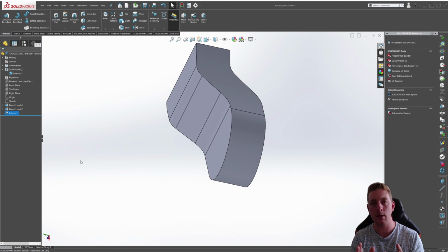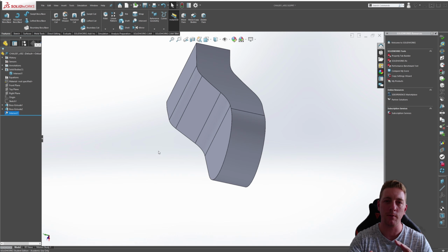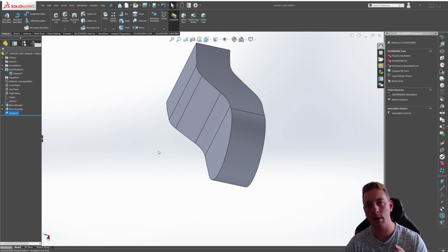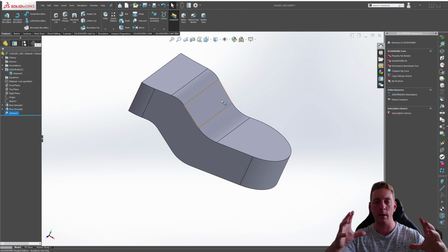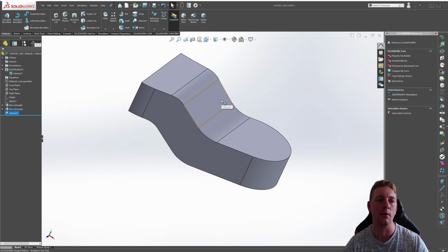So this is a much easier way of creating these weird shapes where it has multiple angles, but from different actual views. So from the front and the top, you can just intersect multi-bodies and create the inside geometry that you need. I find it's a much easier way than creating one large block and then cutting away pieces.